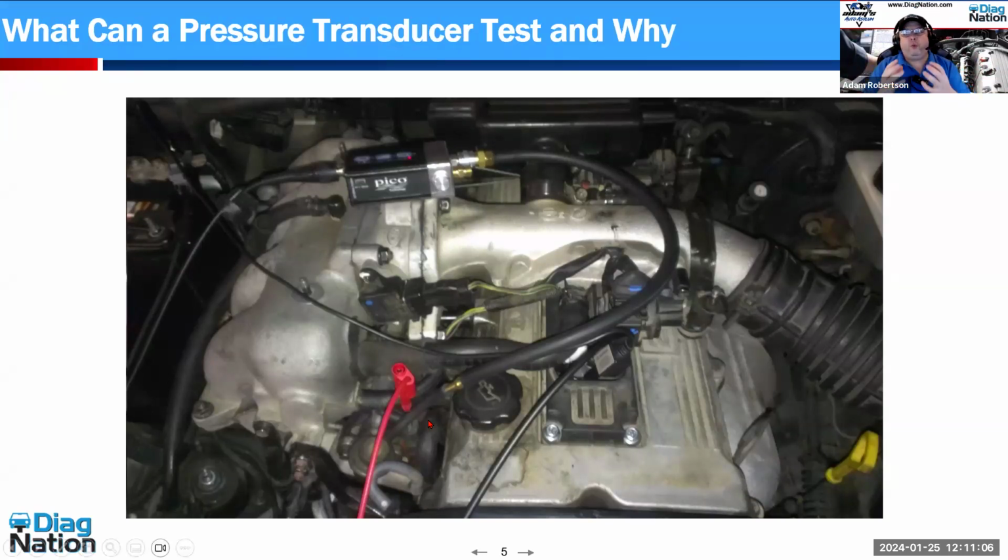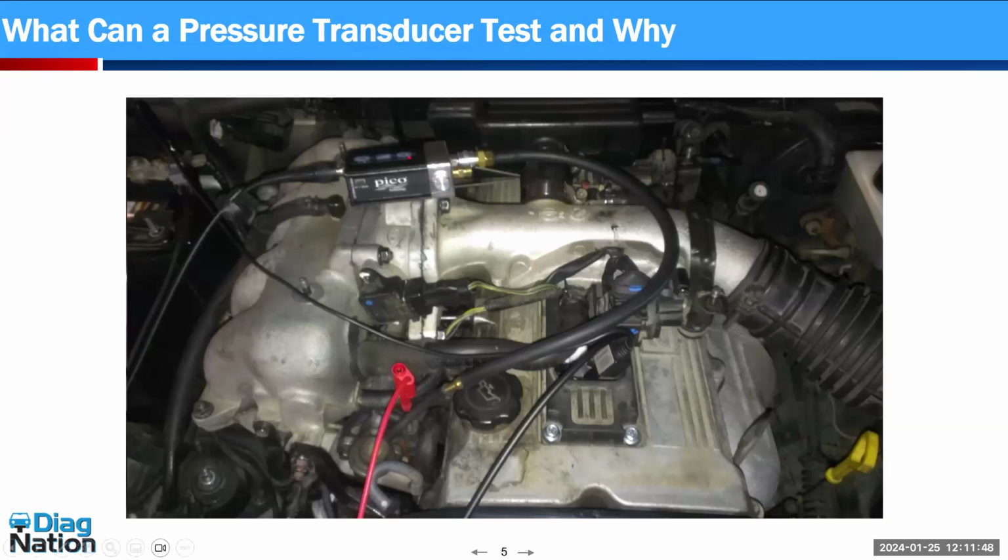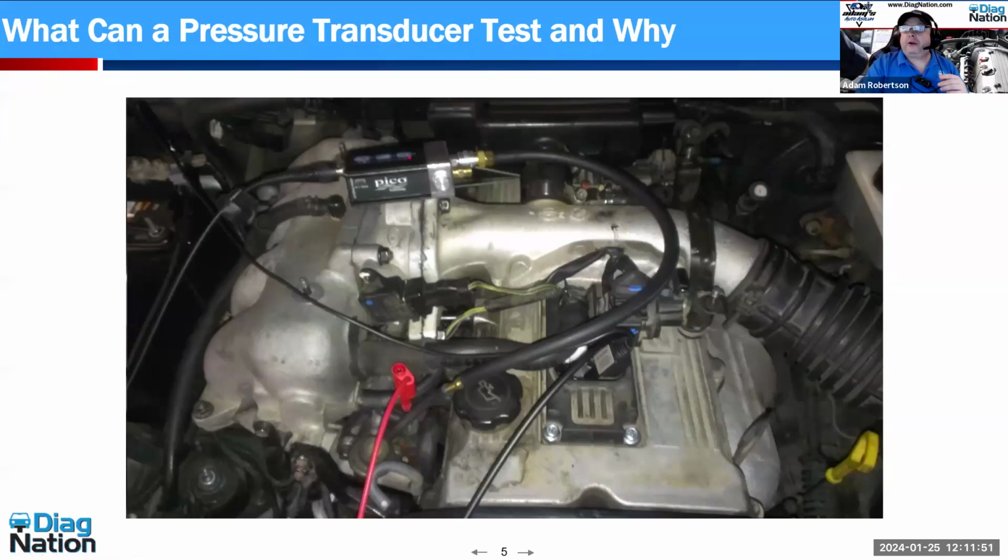But what we know is, with the accuracy of the test equipment we have available to us today and the resolution of the scopes that we have today, I know that inside this diaphragm, I've got the diaphragm here and the spring. I know that the hydraulic pressure in this line, every time an injector clicks, opens, and delivers fuel, there's going to be a vibration created inside that diaphragm. And by measuring that and syncing to the engine, like I spoke about when we started, I can see that not only did injectors click, not only did they fire, but I can tell you if they delivered fuel.